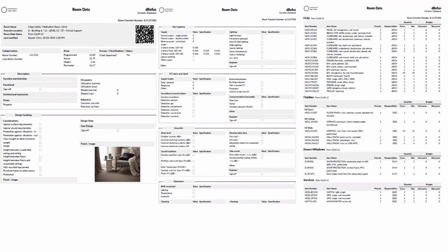Okay. What about if the view that I create is from a linked model? If the view that I create is from the link model, it's not in the main model. So you will need to synchronize that from that particular model. Oh, okay. Or if you have a view set inside of Revit that's linking from the other, I think the Revit function is called Linked View. If you have a view, then you might do that. I'll need to test that workflow out, but in theory, it should be able to do it.